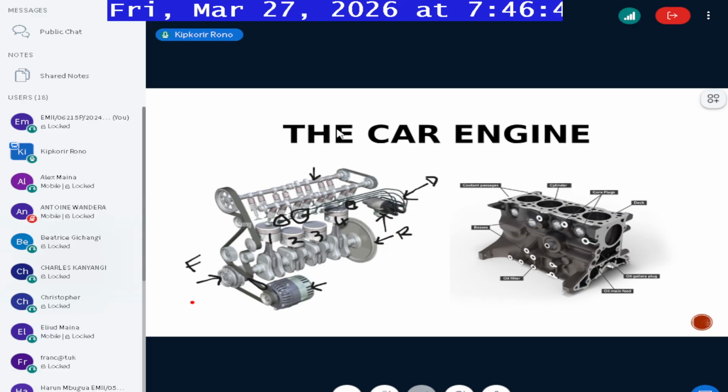So generally, engines, we normally categorize it as that. Of course, this is a crankshaft. I say that the crankshaft rotates 720 degrees for one complete cycle. But for the cam, this cam here, it's 360 degrees for one complete cycle of a four-stroke engine.